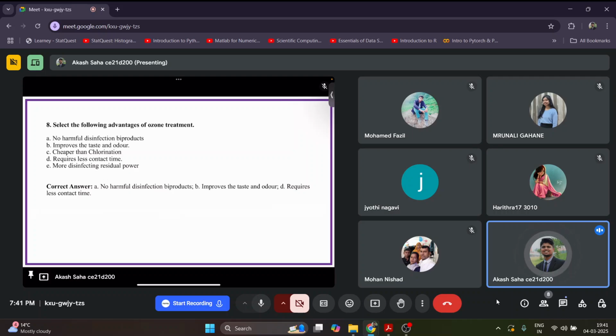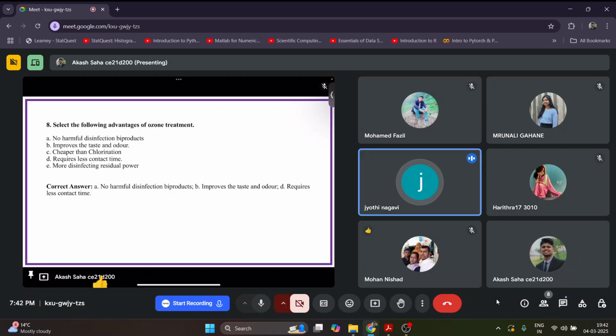Whereas with chlorine, it will be there in the form of chloramines. Mostly hypochlorous acid or OCl-, all these will act instantly, but they will form some chloramines, and these chloramines have a slow disinfection power. So for a long time, they will provide some disinfection power. No doubts?